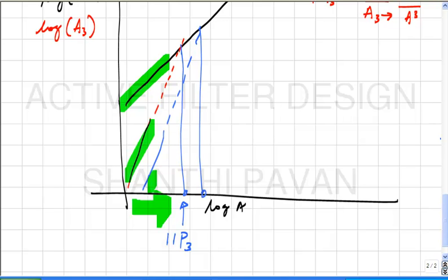So what about bandpass responses? There, almost all the frequencies are high frequency. That's why, when we now measure bandpass filters, harmonic distortion doesn't make any sense at all, correct? Because you have a very narrow band filter. For example, let's say you have a 2 gigahertz filter with a bandwidth of 10 megahertz. It doesn't make sense to do any distortion measurement, because you put in 2 gigahertz, the third harmonic is at 6 gigahertz, which is completely filtered off by the filter itself. So in such examples, harmonic distortion doesn't make any sense.